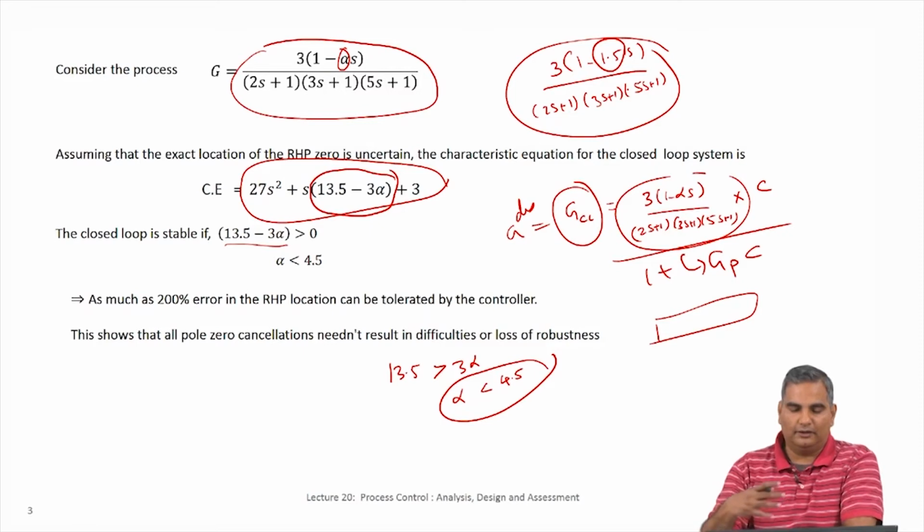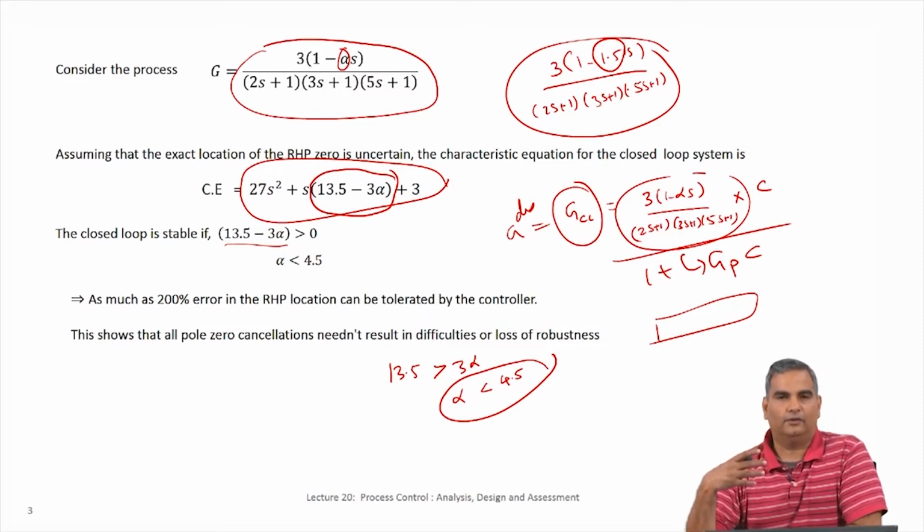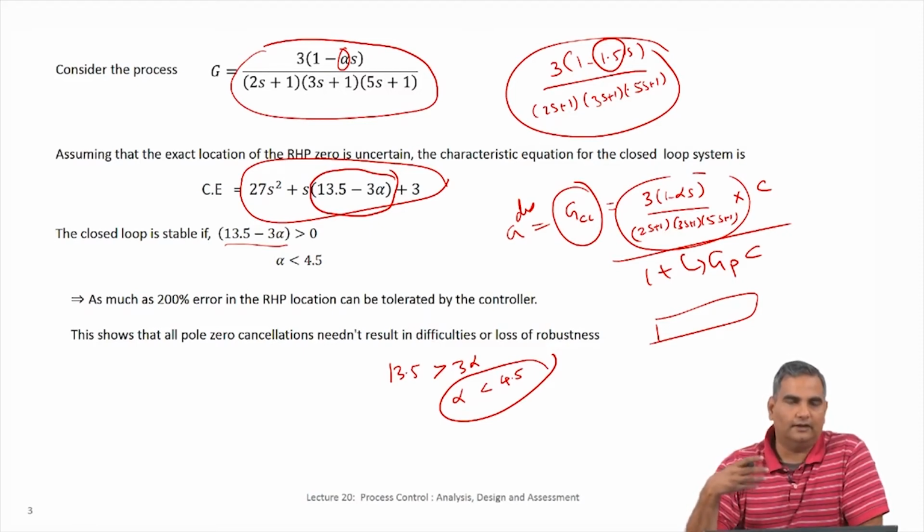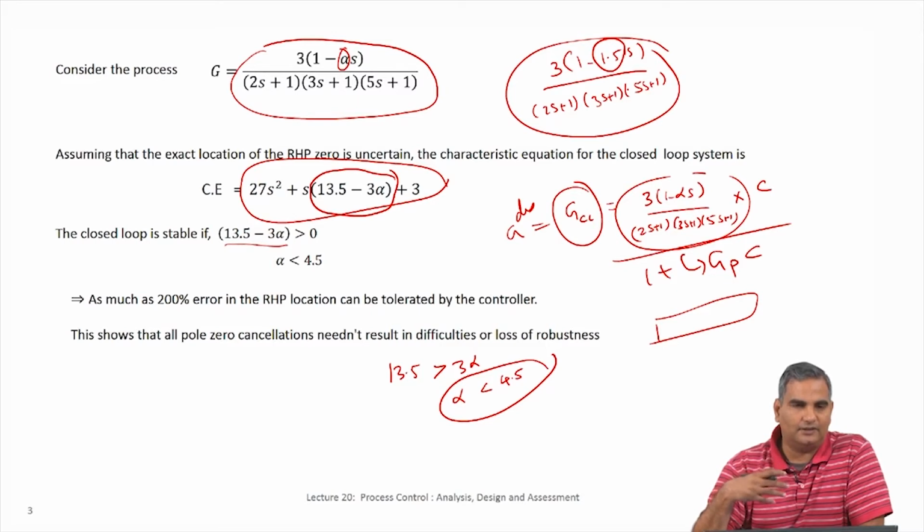Okay. So, this is how we look at how to tune and derive controllers for inverse response systems. The key ideas are to enable us to design a controller. We introduce some performance allowances in our desired transfer function, and then we were able to design a controller which turned out to be in this case a PID form.